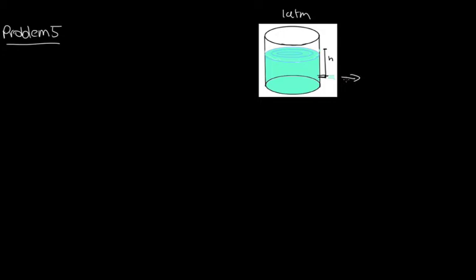So this question is actually fairly challenging. To answer it, we're going to need to use Bernoulli's equation, that the pressure plus rho GH plus a half rho V squared is constant. And so one of the places we'll be considering is right here, where the water's leaving the tank. We'll also want to consider the water just inside the tank, just on this side. So let's call this one location 1 and this one location 2.